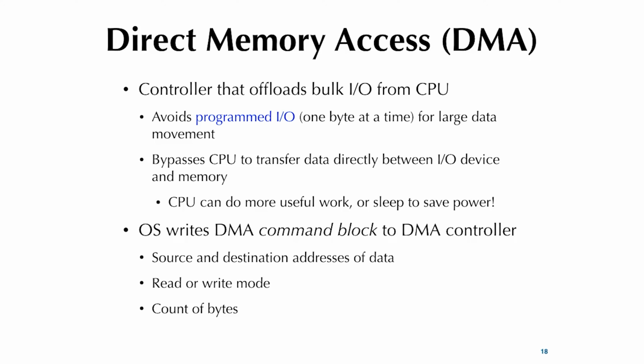But then the CPU also wants to use memory, and the DMA controller also needs to use memory. Can they use memory at the same time? Not really. So what does it have to do? Well, the CPU gets high priority, and the CPU has a cache anyway. That means the memory is not busy a lot of the time because of cache hits, right? So that's good, because then the DMA controller sits on the side and says, processor not busy, not using memory, good, I'm going to steal a cycle, okay?